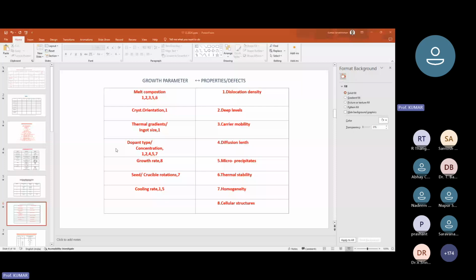There are also other reasons to select a dopant, but if there is a second group element, for example, zinc, or let us say something like magnesium, then that will replace the third group element, or this indium, in which case you will have a deficit of an electron. So this will be an acceptor type, or what we call a p-type.